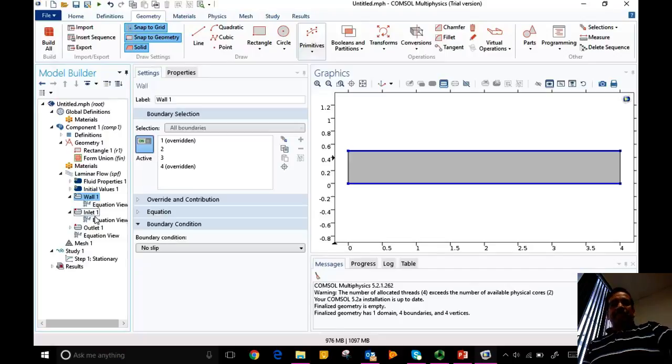So outlet condition, can we change the equations, or do we have to have the boundary equations in the boundary condition? If you are using this particular model, you are constrained to use those equations. But remember, COMSOL is a PDE solver. It evolved from the PDE toolbox. So there is something called a weak variational formulation for solving these differential equations. If you approach it at that level, you can impose any condition that you want. If you can write it down, you can impose it.